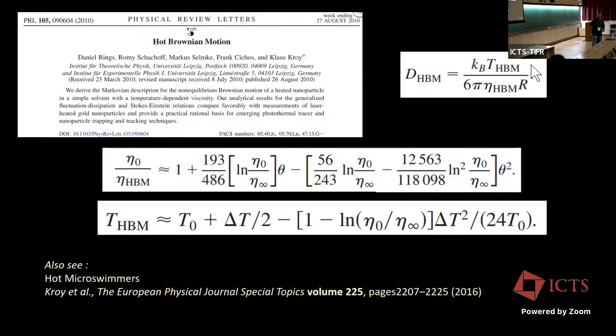Yeah, in fact, it's kind of connected to the temperature increment. For example, you can have an increment as much as 20 Kelvin, which means that you may actually flip an order of magnitude of the viscosity in some particular cases. Again, that measurement of viscosity is non-trivial. It has turned out to be a very challenging aspect in such kind of environments.